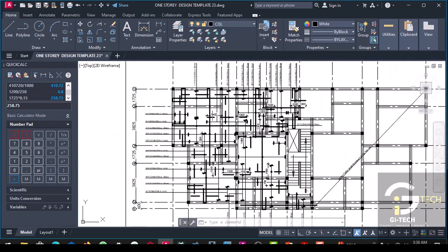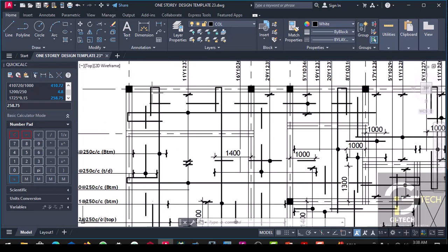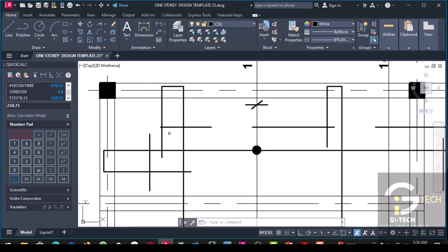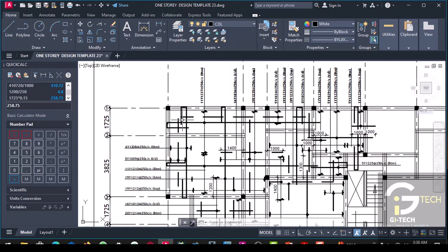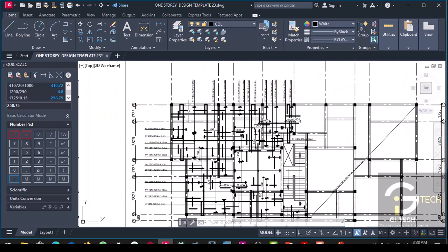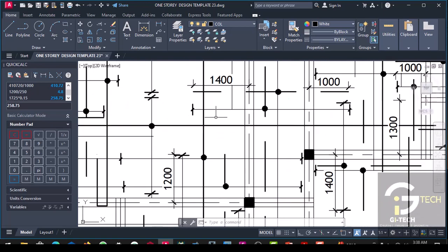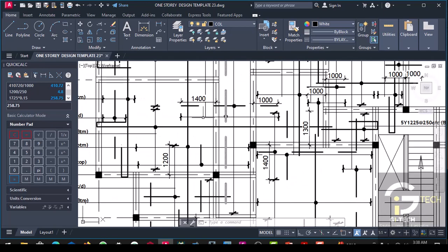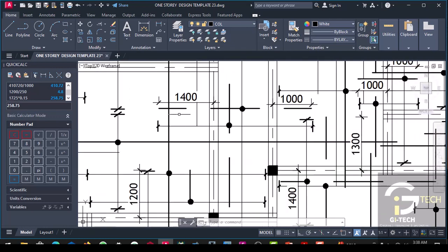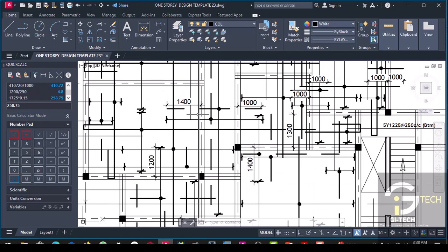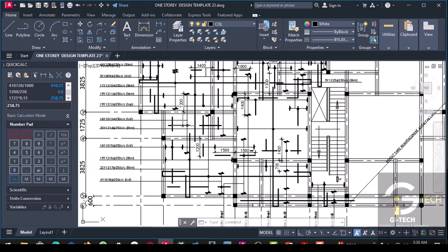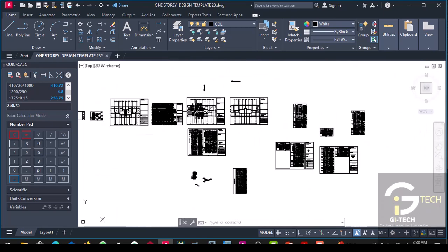Okay. So we have established that for the discontinuous edge, the length of the returning bar should not be less than 0.15 times L. L is the adjacent span of the slab. It should not be less than that, but it can be greater than. Then for the interior support, it should not be less than 0.3 L. So that is what will be guiding us.